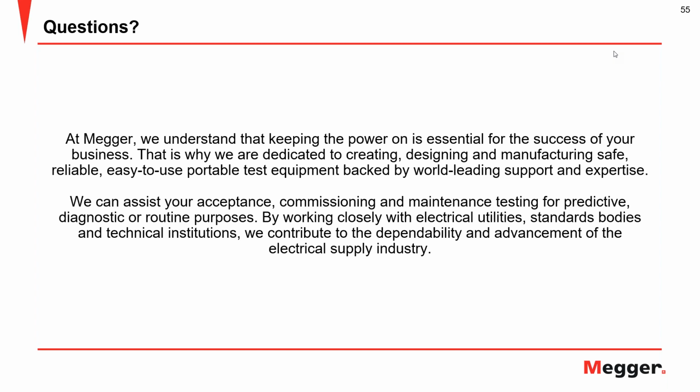Well, the basic problem is the same as tan delta testing on XLP cables. On any of the solid dielectric cables, you have additives added during the manufacturing process, during the extrusion process to be specific. And these additives are also dielectrically active when you test them. And tan delta is a dielectric test.